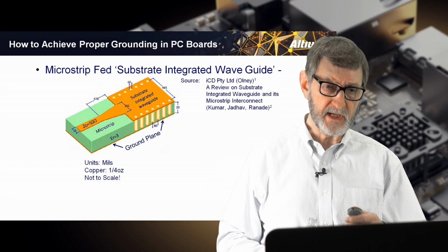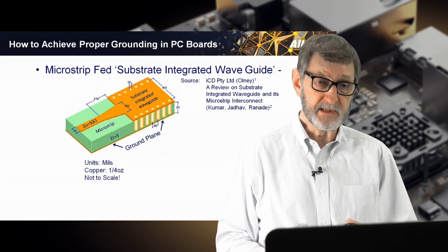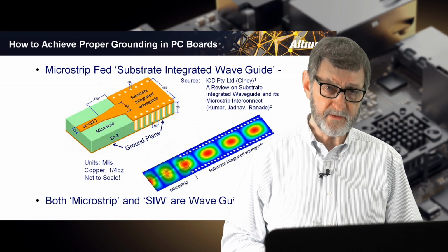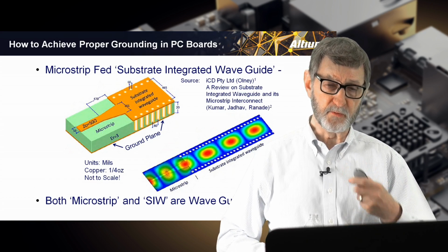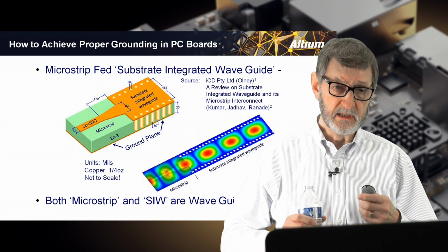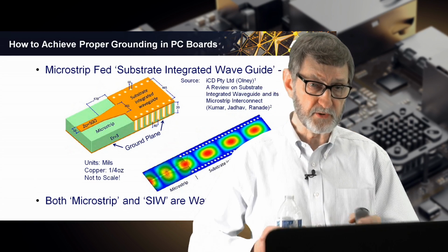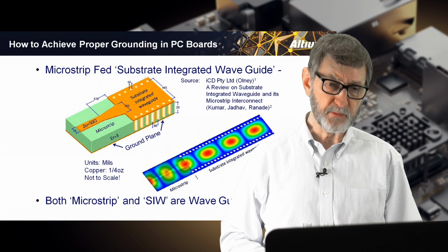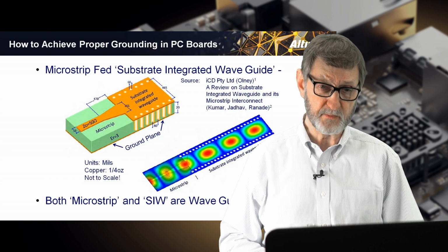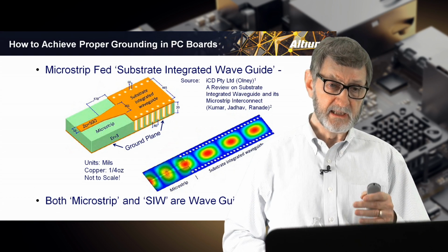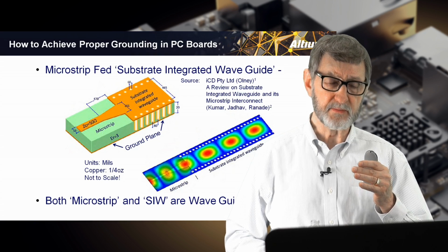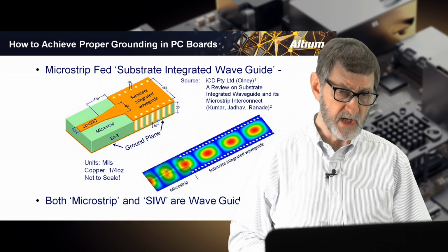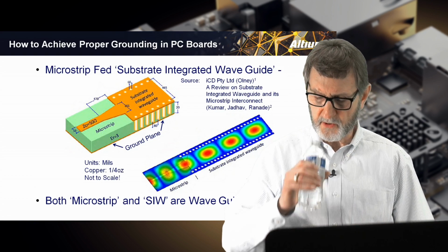There's a microstrip trace above a plane. And the reason this works is because the microstrip is also a waveguide. A trace and a plane form a waveguide, just as a perfectly structured waveguide is designed to conduct one frequency. The difference between a microstrip trace or a stripline trace, which is an interlayer trace referencing a plane, is that those structures can send multiple frequencies. We're not limited to a very narrow frequency range as you would be with a waveguide as shown here.